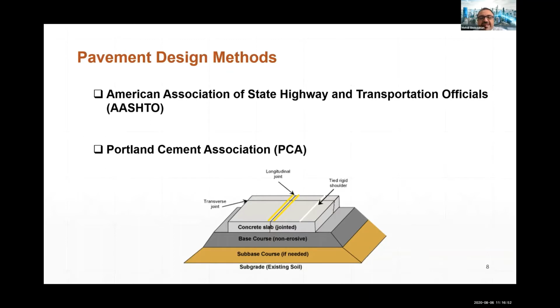Load spectra analysis is more theoretically sound than ESAL, which was recommended by AASHTO. In this analysis, the fundamental stresses and strains are calculated and related to the performance of a laboratory concrete fatigue beam test. Load spectra analysis also allows for calculation of pavement stress due to an axle load and configuration not originally considered in the AASHTO road test.